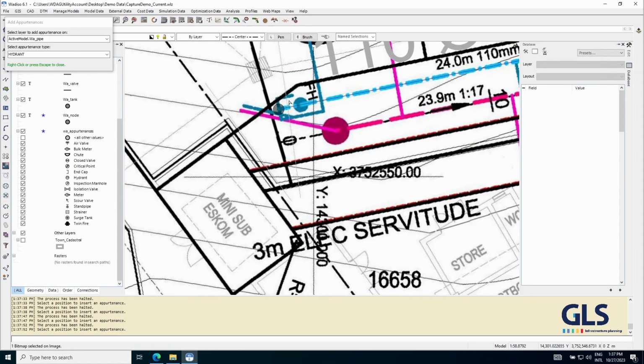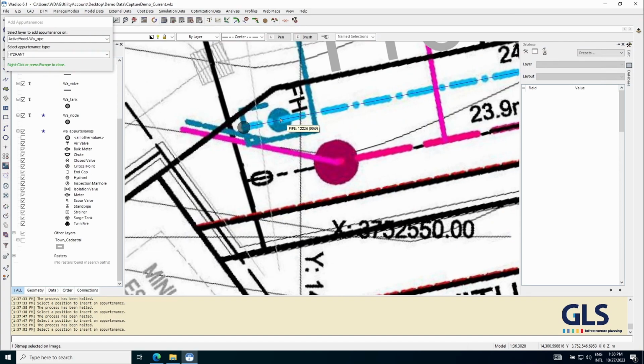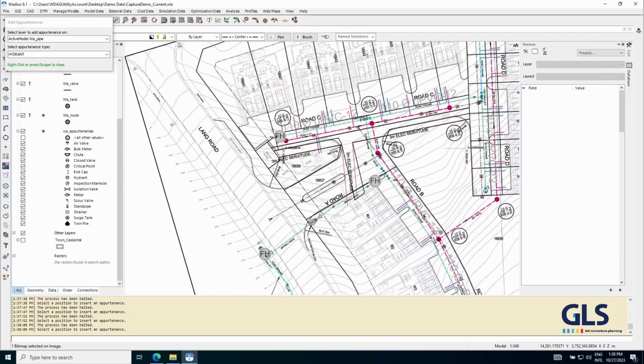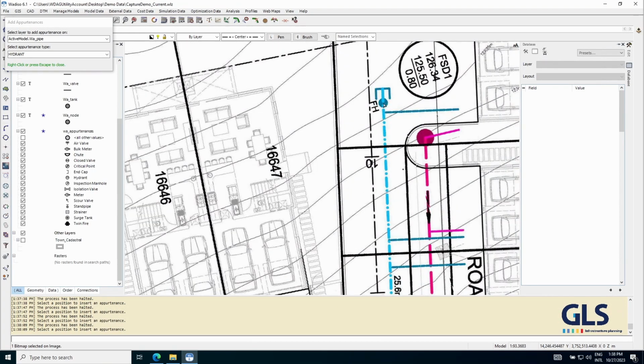down. You will also see that even if I click a little bit off, the blue line is only displayed interactively if you are on a line to insert it on. So if I click off of the pipe, nothing will happen. It will only insert once I'm on the pipe, or it's indicated in blue. And check that, yeah, we have a fire hydrant at this end.